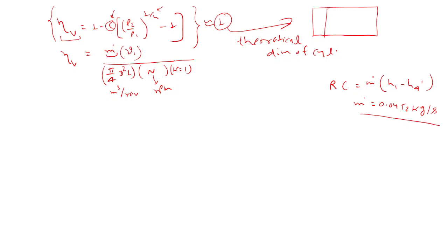So it is in per second, but downside when we calculate this, this is revolution per minute, and this total theoretical volume would be in meter cube per minute. So it should also be in kilogram per minute, because it would be kilogram per minute, and this would be meter cube per kg. Then only both unit dimensions would be the same, right? So what would be then per minute? This would be mass flow rate.